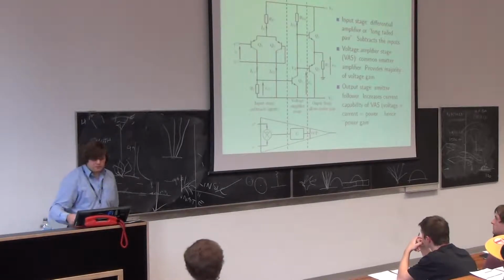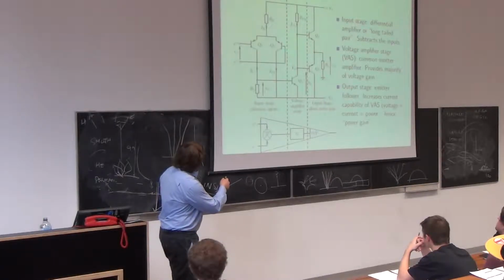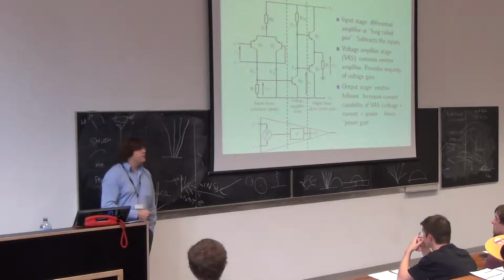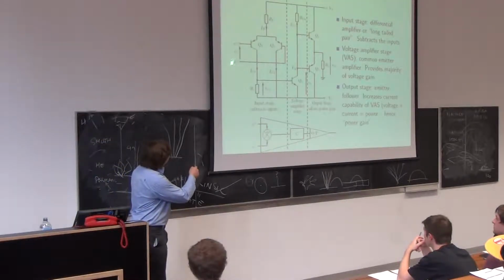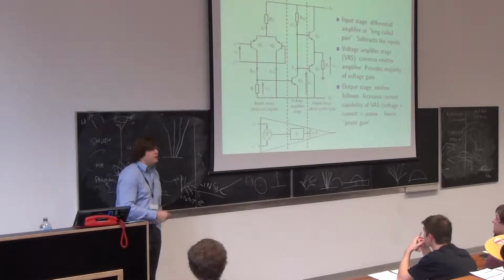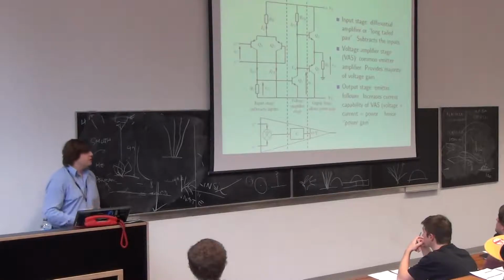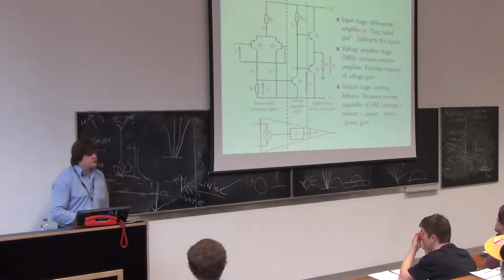The feedback, which is not drawn, we usually have a resistor from, say, there to there, and another one from there to the ground, and that would produce a non-inverting amplifier. Feedback is to the V- node. This is our input node. You could sort it so that it's the other way around, and you could make an inverting amplifier, and that would work equally well, and it would be the same analysis that we did in 118. So those are the 3 stages.